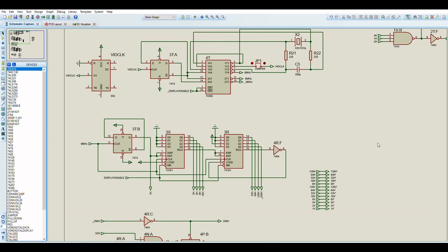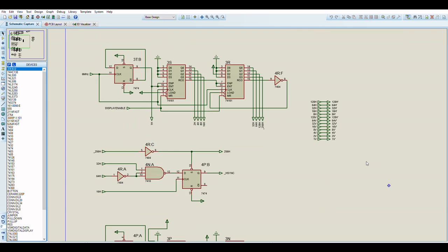And a lot of the logic actually uses very short paths for calculating the output pixel, looking up its color, and then outputting via the palette RAMs, and then going through some resistor ladders to generate the final output pixel. It's actually a really efficient way of operating. Everything is calculated just in time. There is no screen memory for the pixels, at least not for the original Bombjack hardware. Everything is looked up just in time.